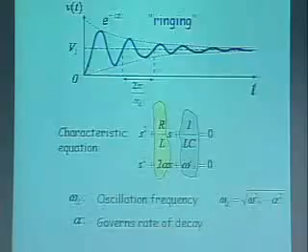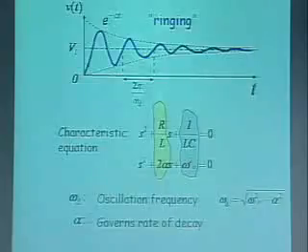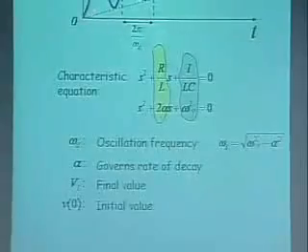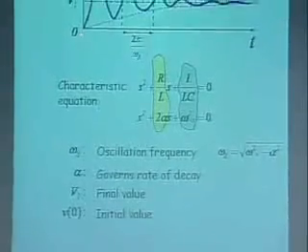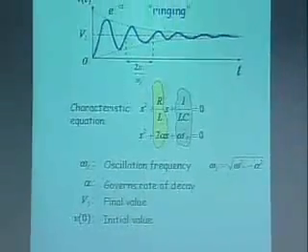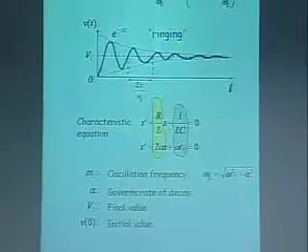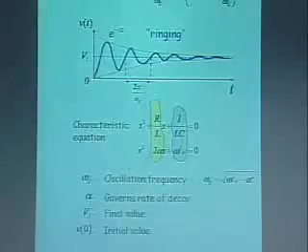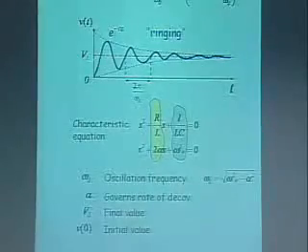It's absolutely unbelievable. Okay? So what are the other factors that are interesting here? Of course, I need final and initial values. I start off at 0. This is my capacitor voltage. If I don't have an infinite spike or an impulse, my capacitor voltage tries to stay where it is and starts off at 0. And the final value is given by VI.